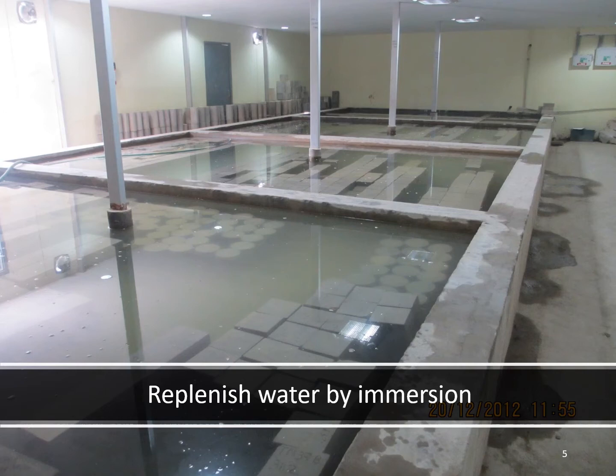If higher temperature gives less strength at 28 days, then you may think you have an issue with the concrete mix, and without checking the temperature of the water, you may try making modifications in your mix designs, which is not at all necessary, because the change in strength is mostly because of the temperature of the water, which is not being maintained at 27 plus minus 2 degrees centigrade.